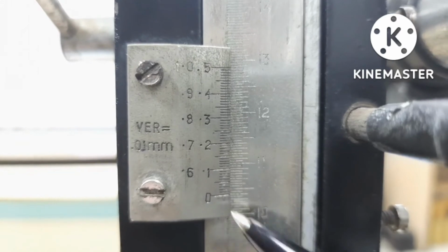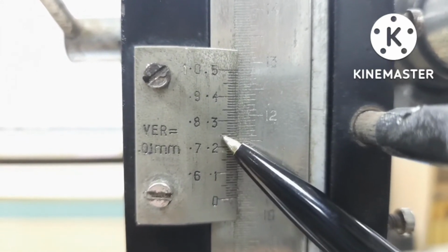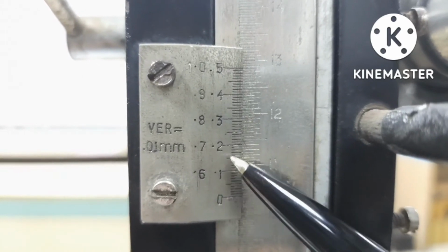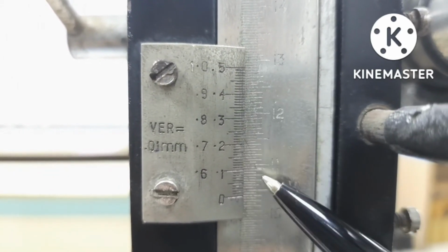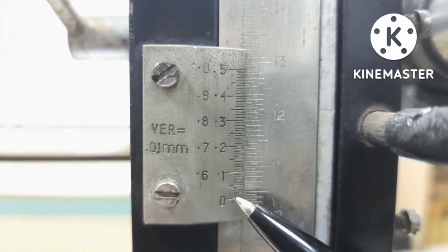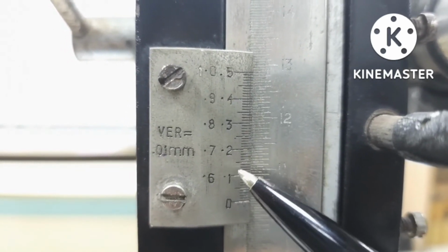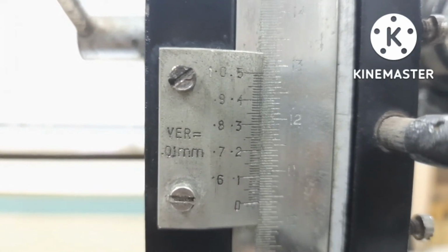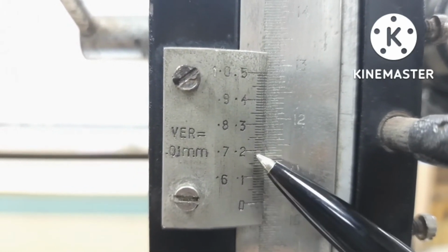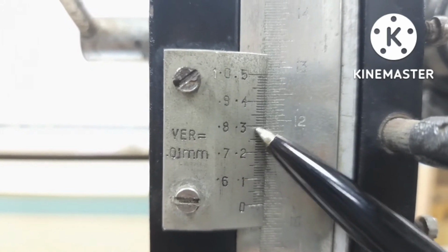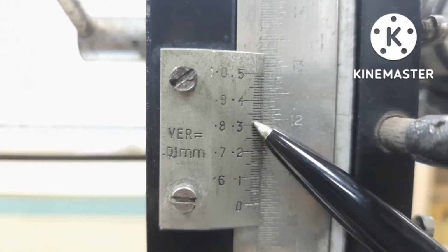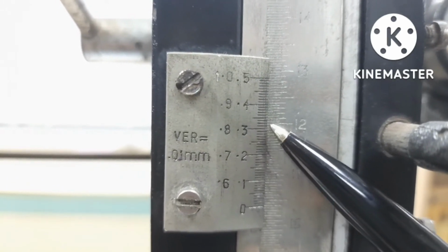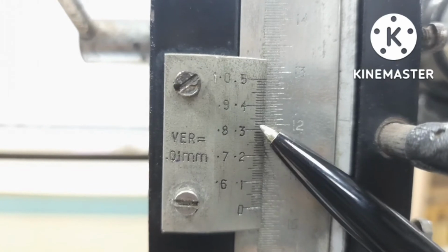So to find out the most suitable vernier reading, you have to check very carefully which mark is coincident with the main scale reading. You may find it is different for different persons, but there should not be so much difference. You will find that this is 0, this is 10, 20, and if we move, that is 30, 31, 32. In my opinion 32 is the proper reading for that case, so we can take the vernier reading as 32.